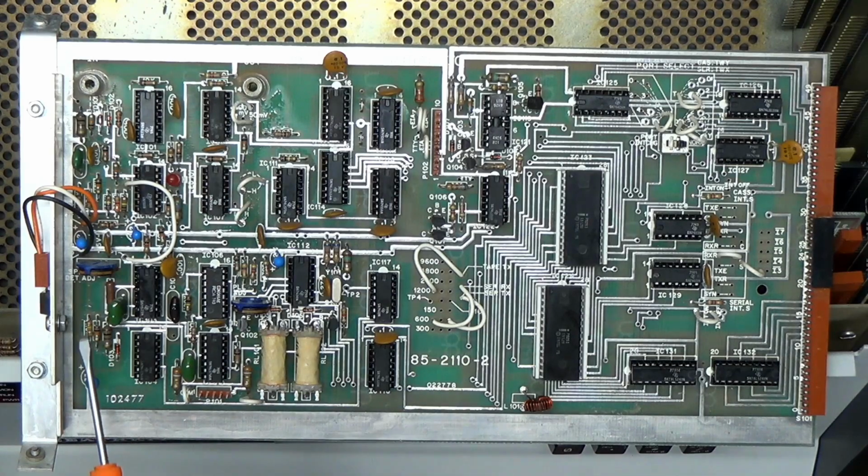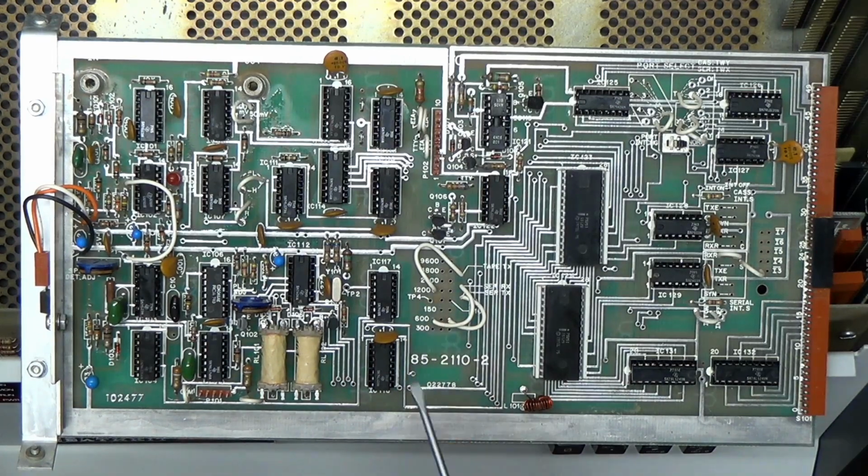There's a pot here for space detector adjustment, so I assume this kind of acts like a RTTY interface. And it's jumpered to 1200 baud, the standard speed, which interestingly is slower than the terminal speed. The terminal is set to 600 baud, which I think was the default speed of the H9 terminal. However, I'll be hooking this up to an H19 terminal, which will run at 9600 baud, so we ought to be able to re-jumper that with some wire wraps there. And I want to try, well, I'll get into what I want to try with the tape interface in a second.